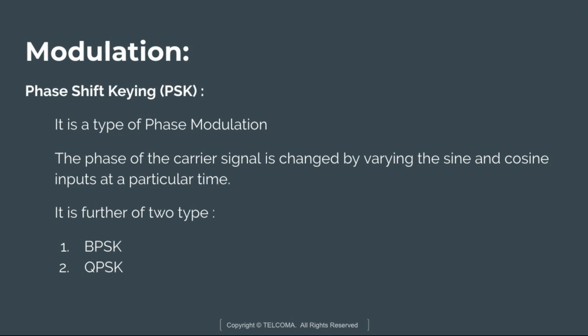Here this is a phase shift keying technique in which the sine wave carrier takes four phase reversals, such as 0 degree, 90 degree, 180 degree and 270 degree. So this kind of technique can be further extended in PSK, to 8 or 16 values also, depending upon the requirement. So these are the types of PSK, that is BPSK and QPSK.